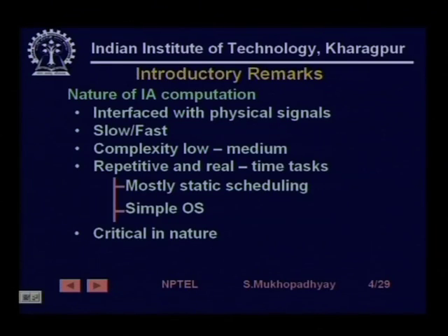Apart from that, one thing is very interesting: when you have a PLC, these computational tasks are very mission critical in nature, in the sense that we do not want to have any kind of errors in them. So, they should have very good reliability and they should always ensure worst case performance specifications. We cannot rely on average case performance specifications. For example, if you have Ethernet, then we know that Ethernet worst case performance generally goes down significantly compared to its average case performance. But here, whatever technology we are using, we should always use worst case performance as the performance guarantee, because the consequences of a task failure could be very great, right.